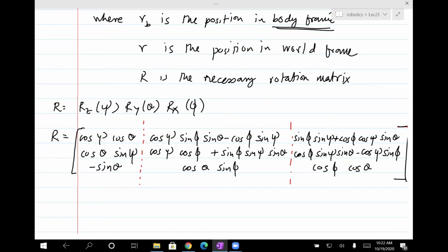So when I showed you those animations last class on 3D rotations, I was actually multiplying rotation matrices in a specific order to get the net rotation. If it was y followed by x, it would be Ry times Rx. That's what I did the first time. And then when I showed you the opposite rotation, I did Rx times Ry, just reversed, and you got the new rotation matrix. Okay, so that is the 3, 2, 1 Euler angles.